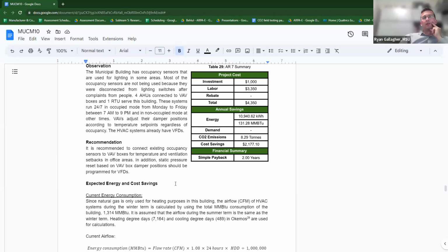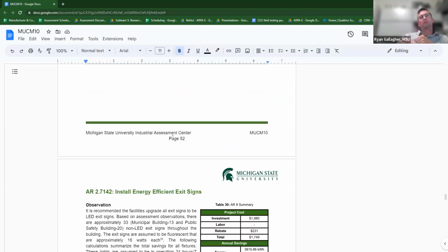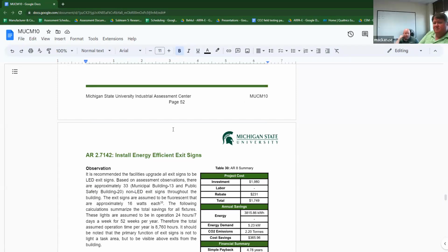Yeah, it's pretty well standard for new construction, and anywhere really where we have VAV boxes, and some retrofit opportunities as we go back through campus. If VAVs have been in for 20, 30 years, we might not have had sensors back then, but putting them in now is pretty common, and connecting them to the HVAC system. We'll shut off or significantly reduce airflow as well as temperature setbacks in those areas. What have you guys found in your draftier buildings or the buildings that don't have interior insulation?